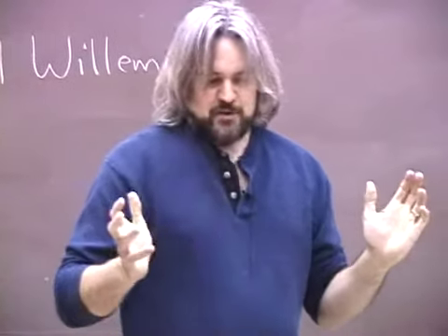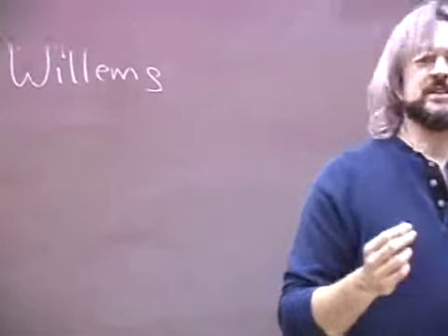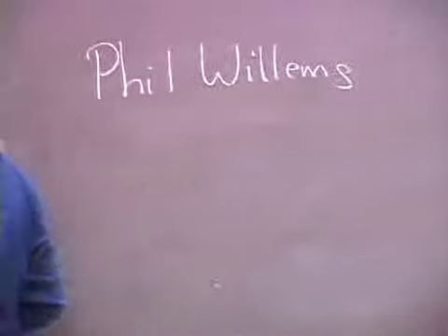So what is thermal noise then? Any object which is at a non-zero temperature is going to have heat energy, and this energy is manifested basically as a mechanical motion of its constituent parts with respect to one another. The temperature is only an average property of a material. The energies of any, say, individual atom in a gas or in a solid body are going to be distributed statistically with a distribution which is determined by this average temperature. For example, in an ideal gas,